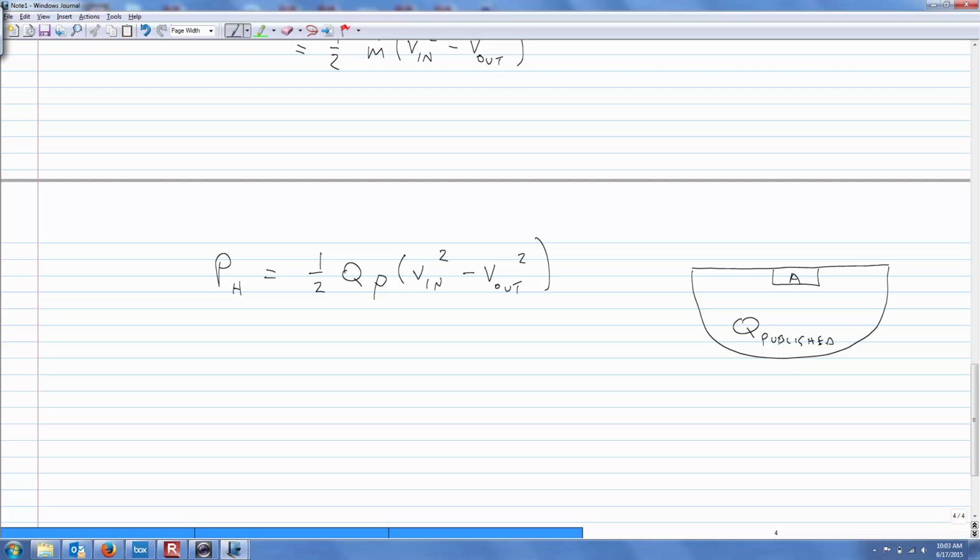You got any ideas on that one, Austin? Like I said already, if the entire river flowed through our technology, we know we'd capture all of it. So the river itself, I'll just put this as a river. What we're looking for is Q micro hydro. We'll estimate what the area of the river is. We'll get the depth, we'll measure the width, and they give you a cubic feet per minute. Yeah, exactly. And that's what we're working at, volumetric flow rate.